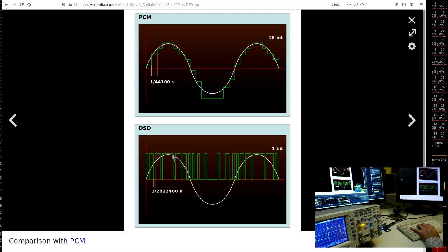Super totally simple, and the cheapest form of this actually, of course the audiophile stuff is doing this in some separated integrated circuit, but the poor humans form of this is simply to pass this high frequency value through some low pass filter with some resistor and capacitor, that we will do tomorrow or something of that sort, and filter all this high frequency noise that is ultrasonic harmonics anyway and you will not hear. So smooth out the signal through a low pass filter, in the cheapest form a capacitor and resistor, and that's it.